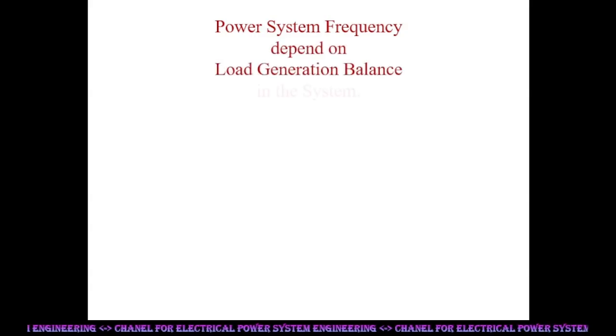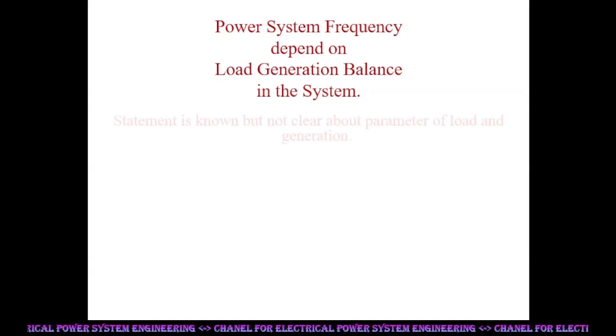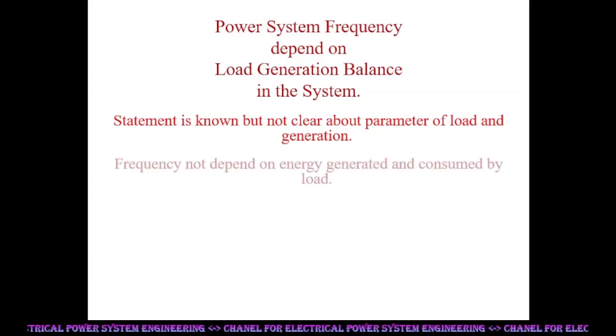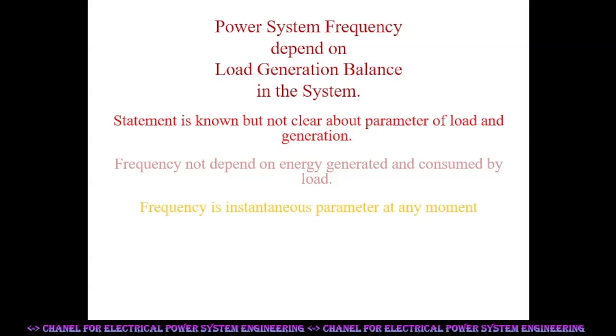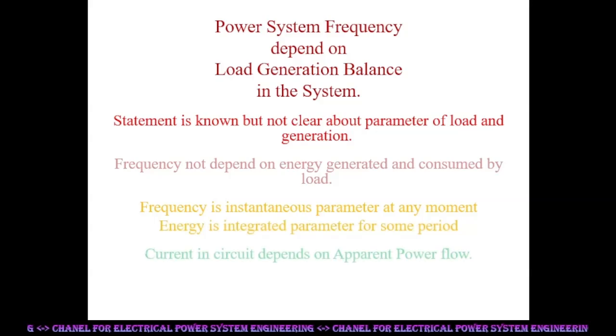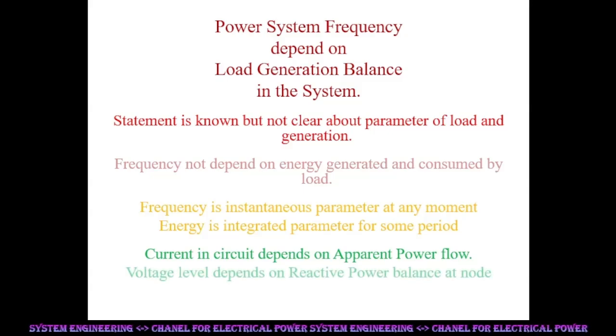Power system frequency depends on load generation balance in the system. This general statement is known to power engineers but not clear about parameter. Frequency does not depend on energy generated and consumed by the load. Frequency is an indicative parameter for any instance, whereas energy is an integrating parameter for some period.